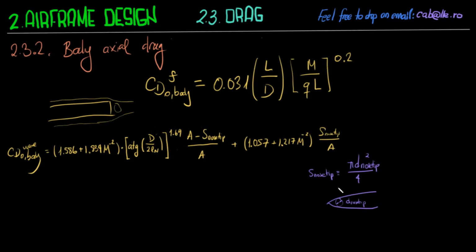So if we kill this pointy edge and give the nose tip this slight curvature, which will ease a lot all the stresses on the tip, the drag is going to be slightly higher if you round the nose, but it's going to alleviate all the mechanical stresses and also the heating.